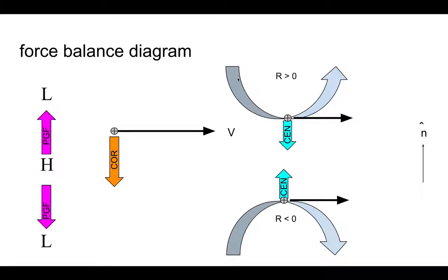And so here you're going to see these arrows that are curved, and this indicates counterclockwise turning. When we have that sort of flow curvature, we denote that the radius of curvature is positive in that situation. And then the centrifugal acceleration acts outward, which is in the minus n direction in this case.